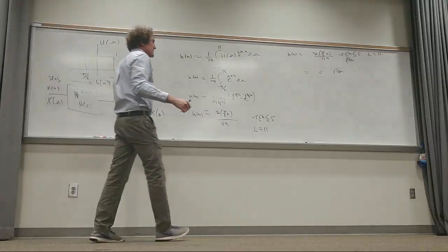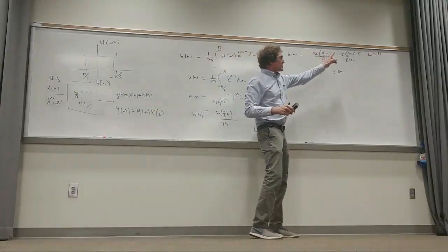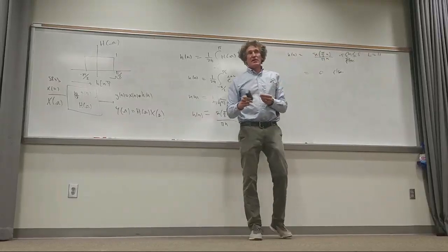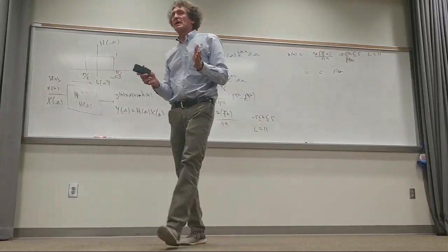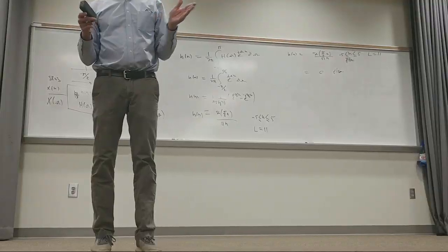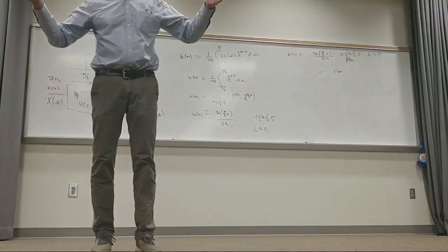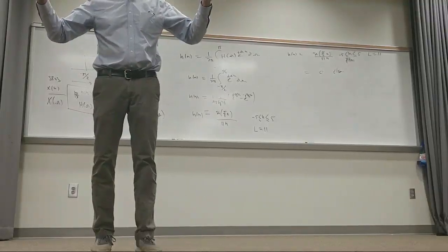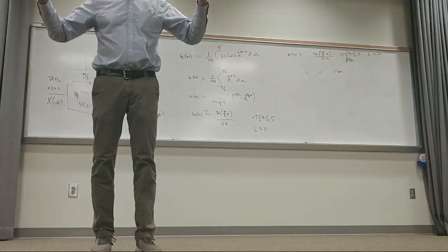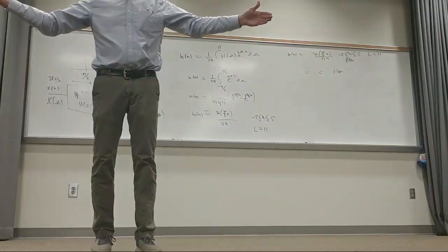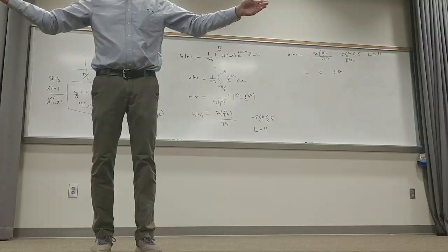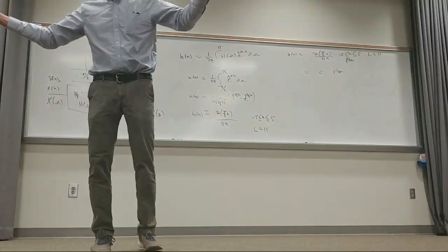So if I take this here, it starts at minus 5. I'm going to apply a Hanning window. This is common for almost any type of filter, because anytime you do this truncation business, where you have a filter response and you truncate it, automatically, if you don't do something, you get these side lobes that are unwanted. You're going to get things that are unwanted in the frequency domain. All right, class? This is the reason I'm doing it.